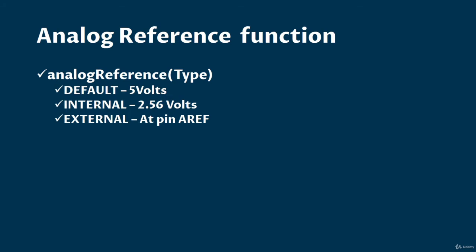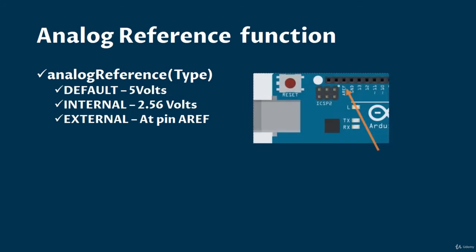If you select the type EXTERNAL, this time you have the freedom to choose any voltage between 0 to 5 volt. You should give that voltage at the analog reference pin.